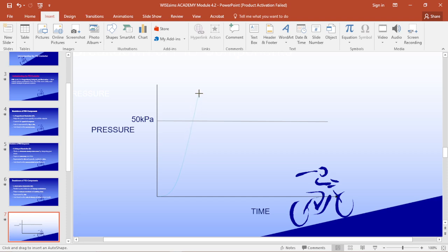Once it overshoots, we have to allow it to oscillate a little bit. This is called oscillation. Now it goes below. That's how it tends to be. From the start point to getting to the set point, that's the job of your P controller, the proportional controller.